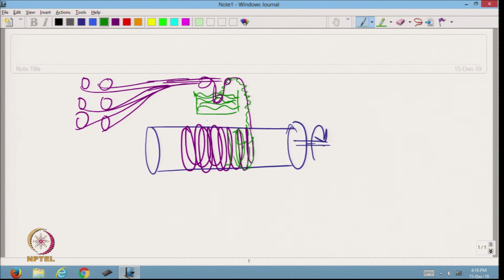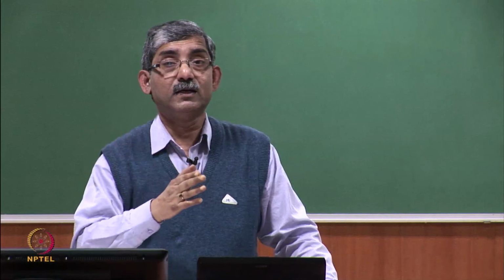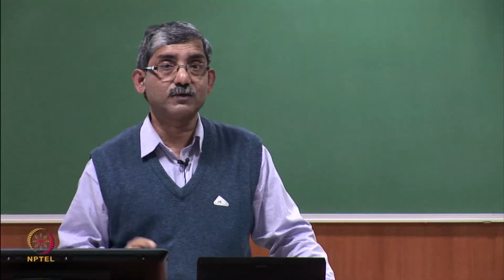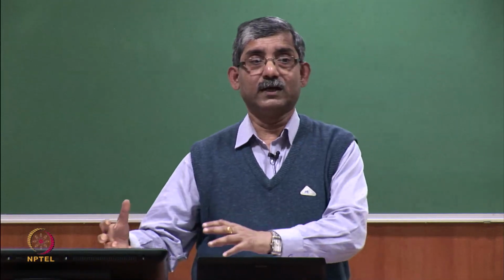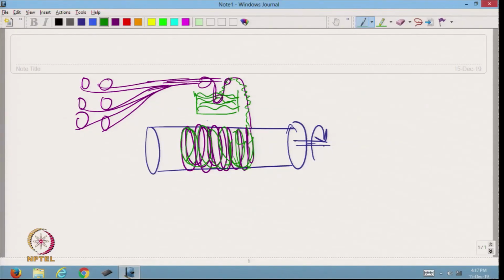So, the filament along with the resin, they are winding on this cylinder, and here after winding they get automatically solidified, because the resin is thermoset resin, and after solidification we can take it out from this base cylinder. So, this will ultimately form a cylindrical shape composite.